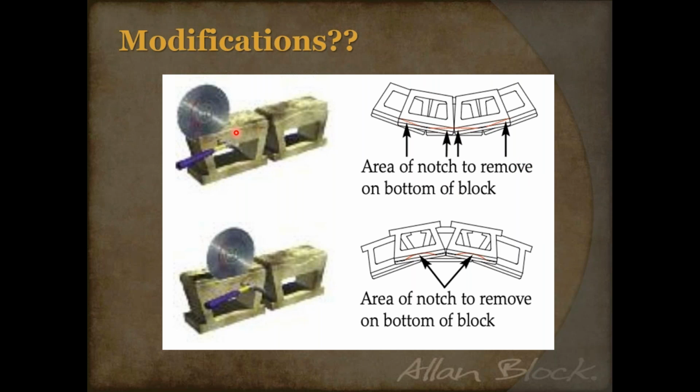You can actually modify the block. You can deepen the notch, and it's important to deepen the notch. Never modify the lip. The lip is our shear key. That is our setback. So you always make the modifications towards the bottom of the block, where if you deepen that notch, that allows you to slide that block forward and hide that setback or that top of block, and it still maintains that 6-degree setback.